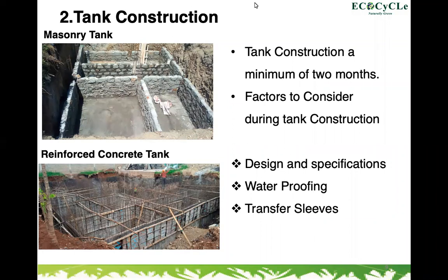So those are the few factors I could mention that we have to consider during the tank construction. Another one that maybe we may not have indicated there is the invert level. So depending on the ground and where the sewage is being collected from, we have to consider the invert level.